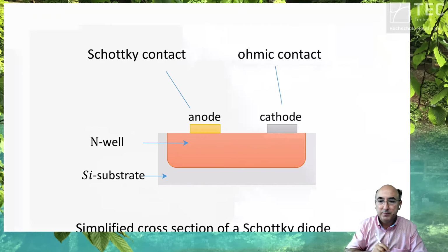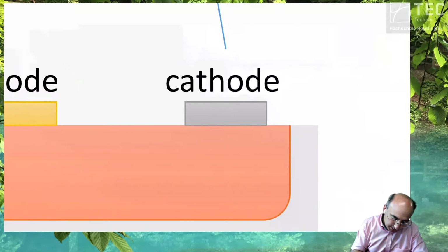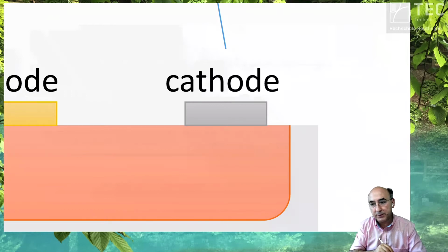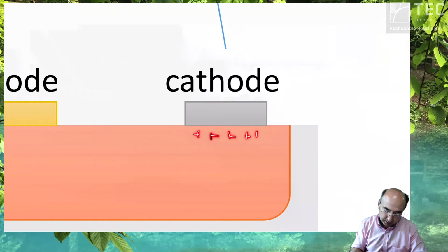Then you heat it up. After heating up, some parts of these metals diffuse into this semiconductor and make this area highly doped. What we have said about highly doped areas: they are metallic, degenerate doping. We learned that at the beginning of our lectures when we talked about doping. If this doping level is so high, it is higher than the states which are available in the silicon.